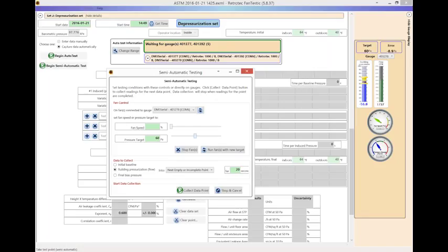Try to do speed or pressure? I have pressure set here. Well, actually, it's already operating, so yeah. It's clear that yes, it can achieve 60 pascals. You can see it overshot there a little bit. It's now at 61.7. So what that's telling us is that fan is working on both channels. Channel A is giving you the pressure, channel B is giving you the flow, and using the same method you can go and check each one of your fans individually to see whether it's working.